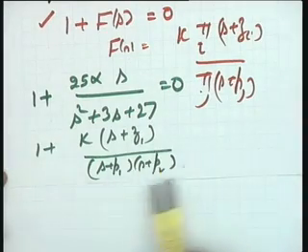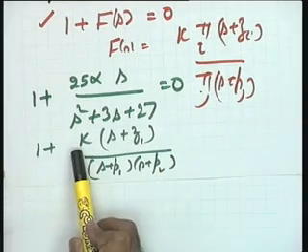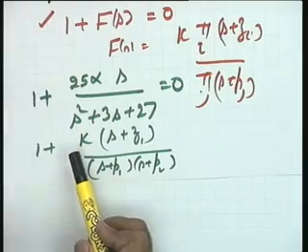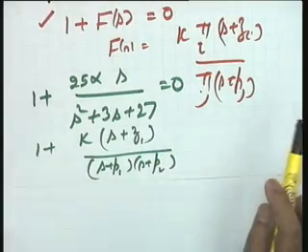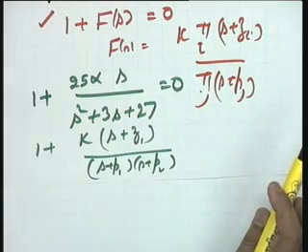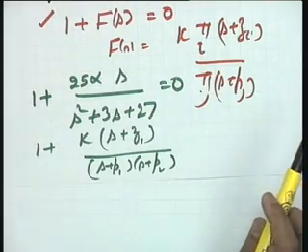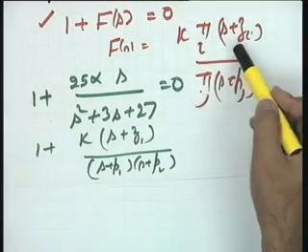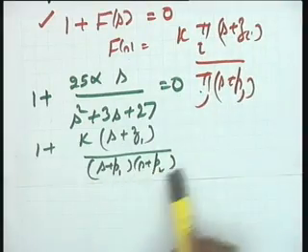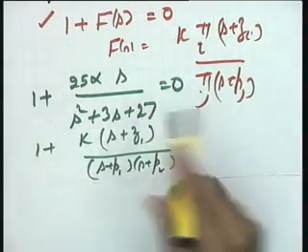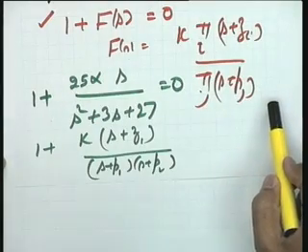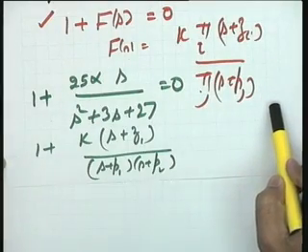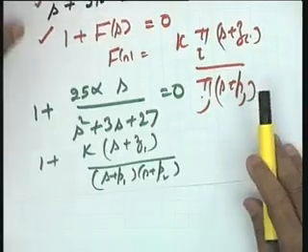But when I am taking poles and zeros and the gain K, you should keep in mind that it really does not mean that these poles and zeros are necessarily the poles and zeros of the open loop transfer function, though that is the case we very frequently come across. But there may be a situation of this type where these poles and zeros have been created so that the original characteristic equation can be written in this particular format. Okay, I hope my point is clear, and the design examples will surely follow, even on tachometric constant and all that.